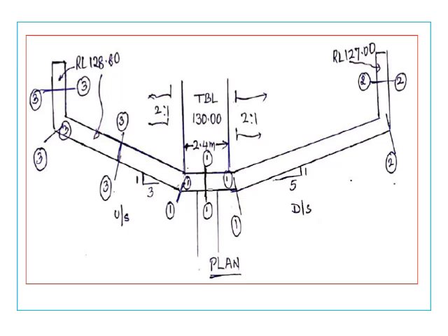We know that for any wall, the top of the return wall should not go below the ground level. We know that the ground level is at 127, so therefore the top of the return is kept at 127. Now the wing wall will slope from 130 to 127. Generally this downstream wing wall is given a slope of 1:5.